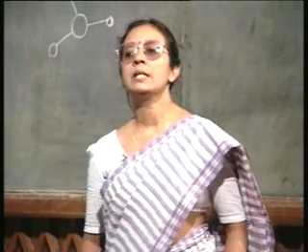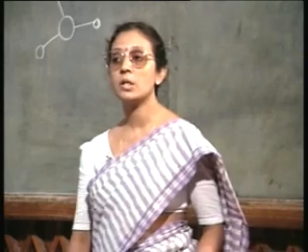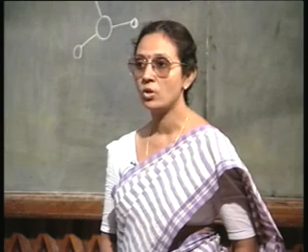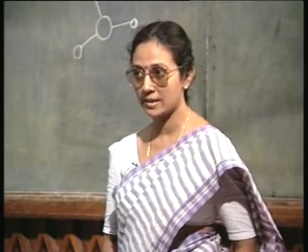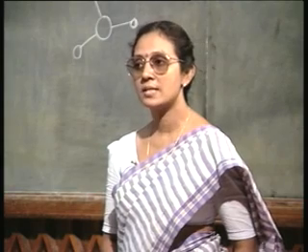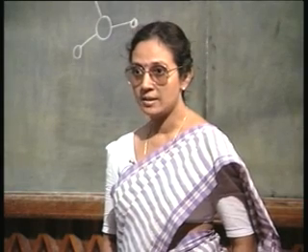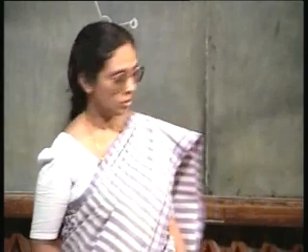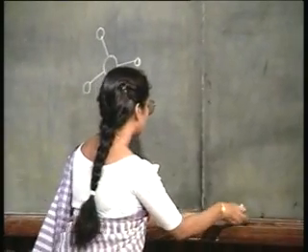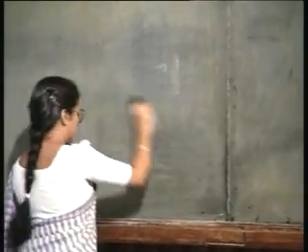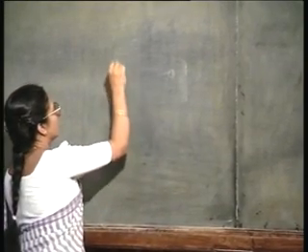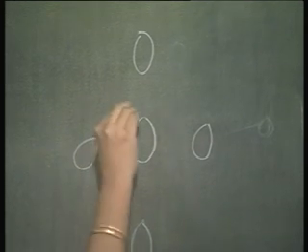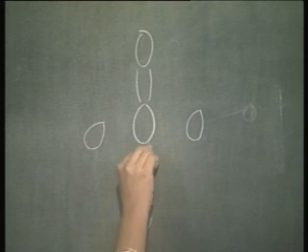Most often we say that an impurity atom is going to be electronically active, that is, it is going to act as an active dopant, an active donor or an acceptor when it is replacing a silicon and taking up its position there. You all remember, I suppose, that we say these are the bonds which are formed.